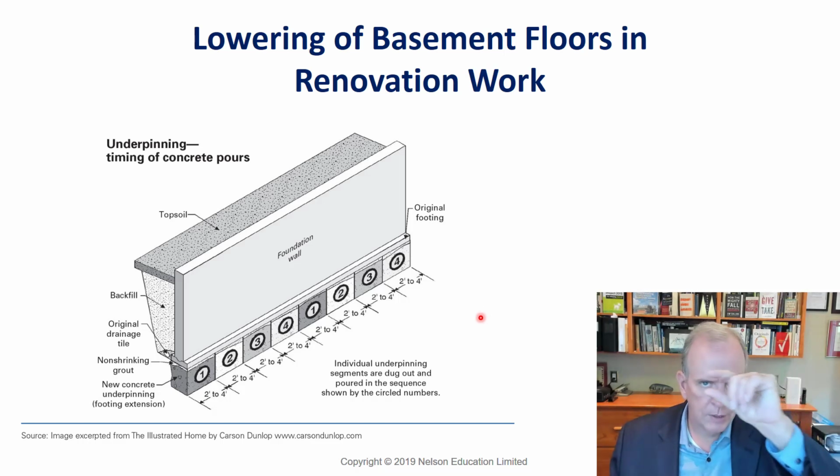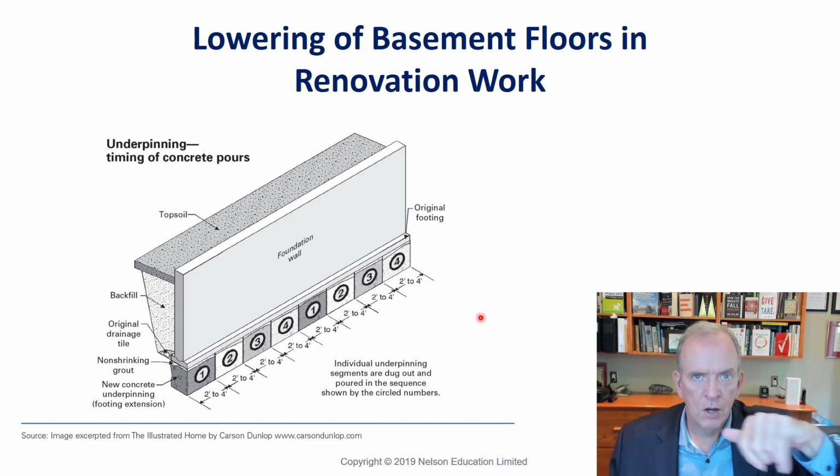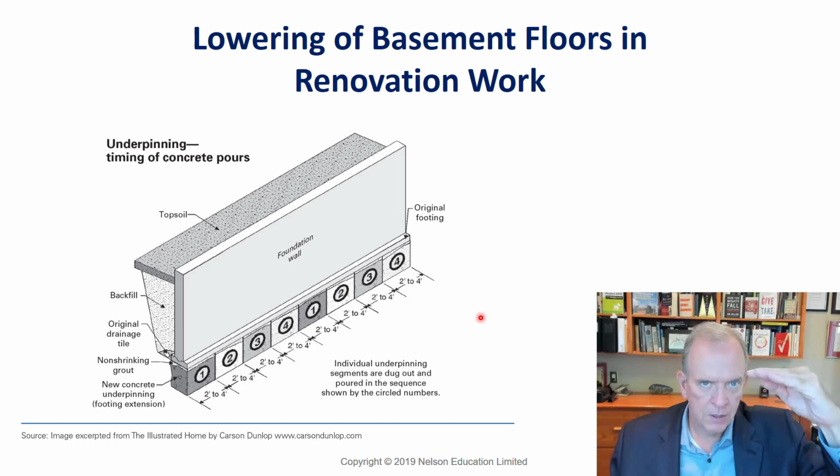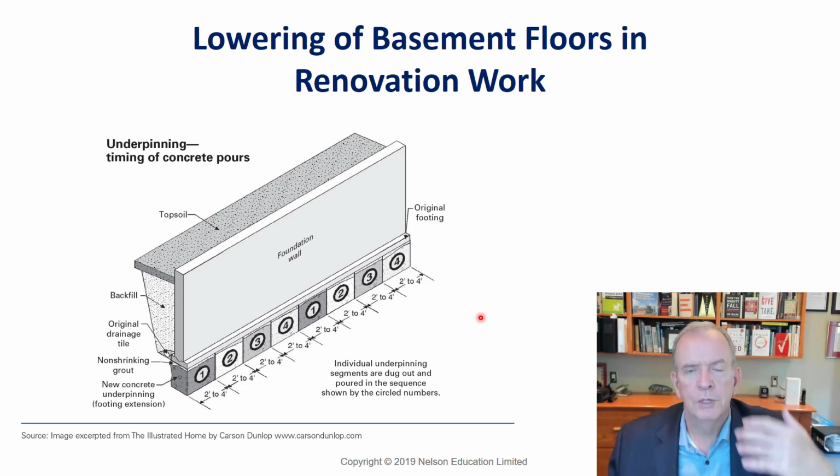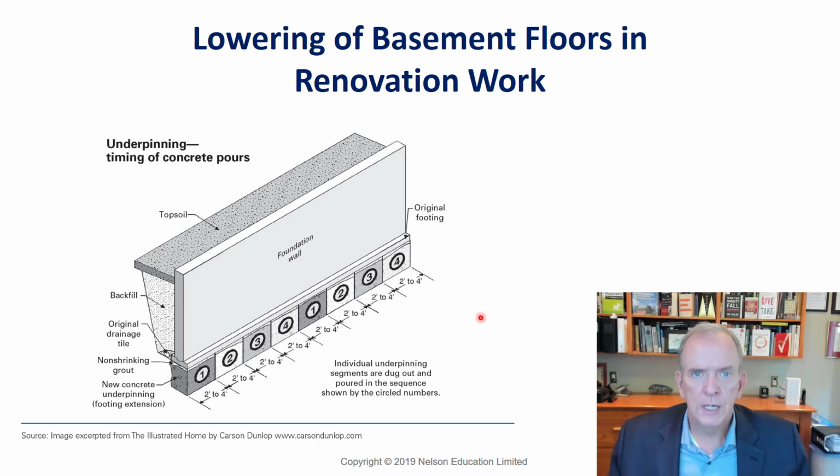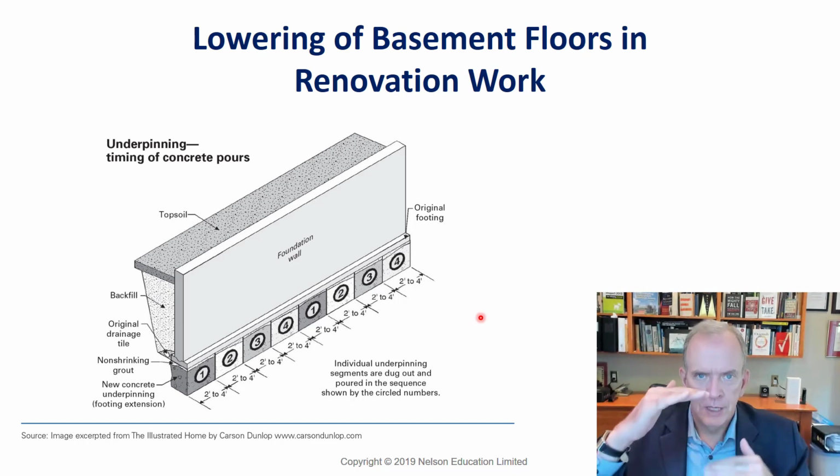Typically you'll let it dry with a little bit of a space, and you'll pack a non-shrink grout in that space, because concrete shrinks a little bit typically. So what you do is purposely leave a little bit of a space, and you pack in a special non-shrink grout mixture, which has a high compressive strength, that is actually tuck pointed into that space right the way back. And then when it dries, it won't shrink, and it will take on that bearing load from above. So underpinning is a good way of gaining a lot of square footage.